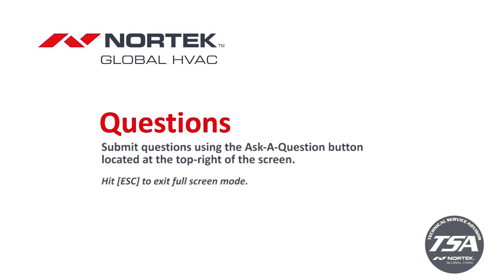Got a question from Tom. Tom is asking about subcooling on TXV systems, saying it's not recommended. So he's basically asking, is subcooling used for a TXV? You're right. If you have a system that is TXV driven, you will use the subcooling method.